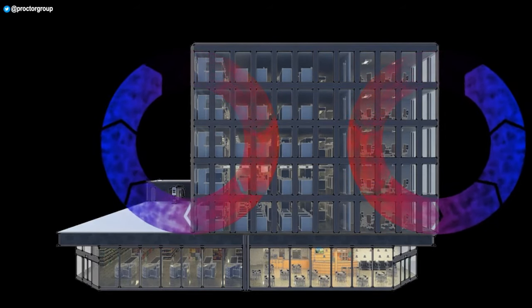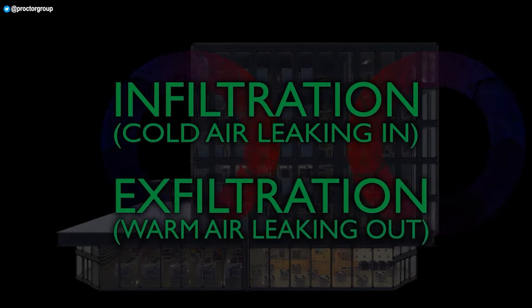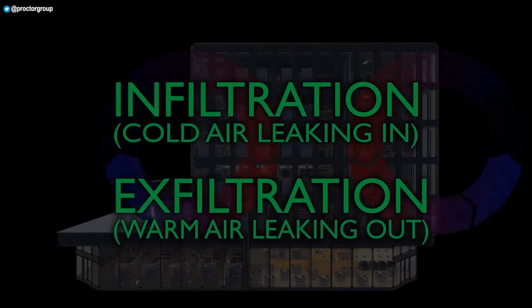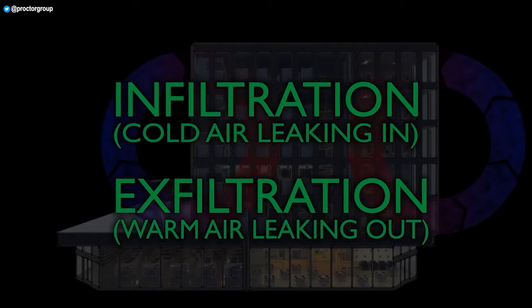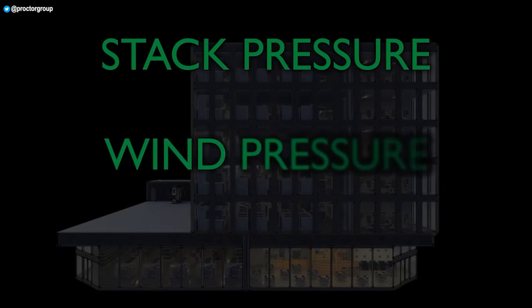The two basic factors affecting air movement are infiltration and exfiltration, air moving in and air moving out of the envelope, and there are various mechanisms which drive this. The three main air pressure phenomena affecting air movement are stack pressure, wind pressure, and mechanical pressure.